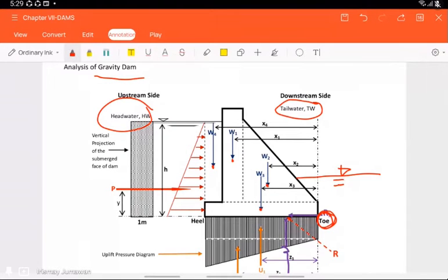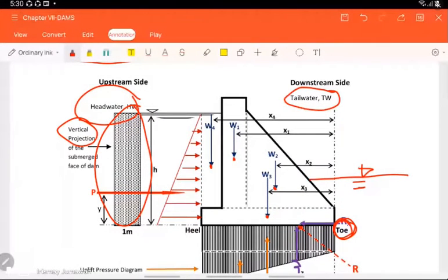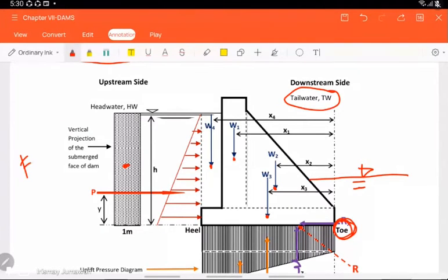if you remember in your fluid mechanics, the vertical projection of the dam is a rectangle. So ang vertical projection sa imuhang dam. So you have there, to determine the pressure you have the formula F is equal to gamma h bar times area, provided your vertical projection is rectangular like this.